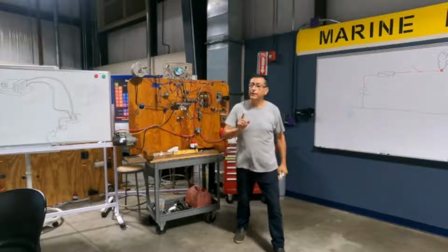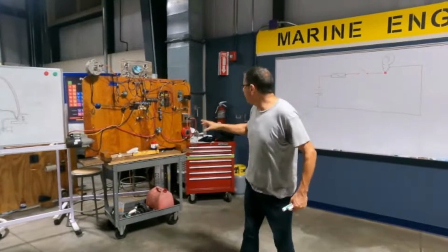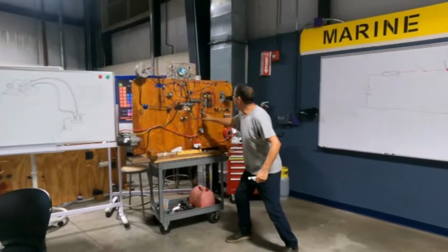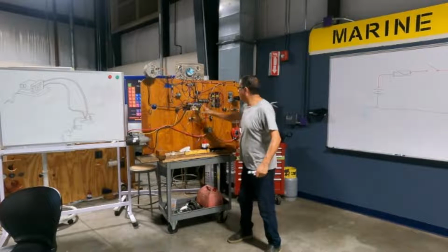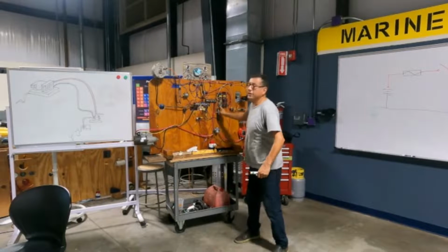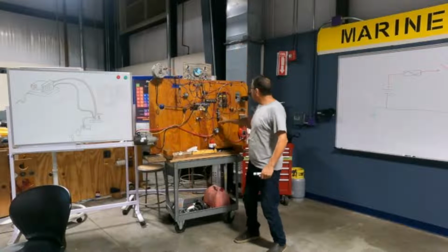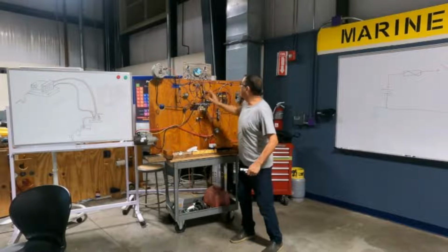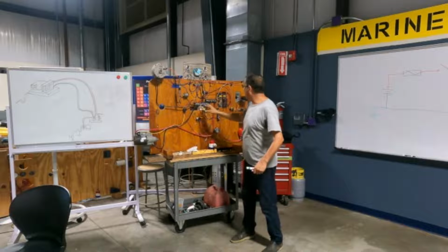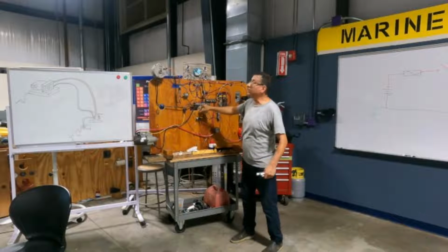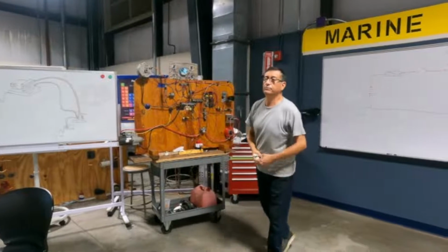That's the most important part. The negative bus bar. How many negative bus bars do I have in this boat? 1, 2, and another here, 3. Oh, 3. This one is in the DC panel. This one is in the flybridge, and this one in the main engine room.